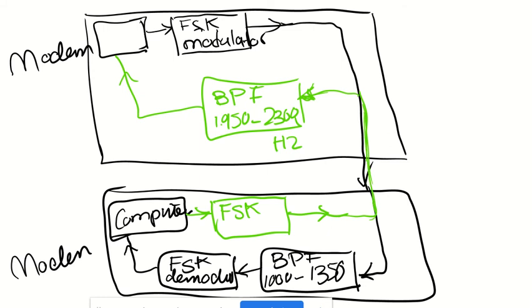Other than that, by now, you should get an idea about a modem: you have some binary data going out, some ones and zeros, which go to your FSK modulator. This is one kind of modulation. I'll talk about others later. This is, for example, for telephone audio, sending and receiving voice. So it goes, and with modulation, you can send it through long distances.